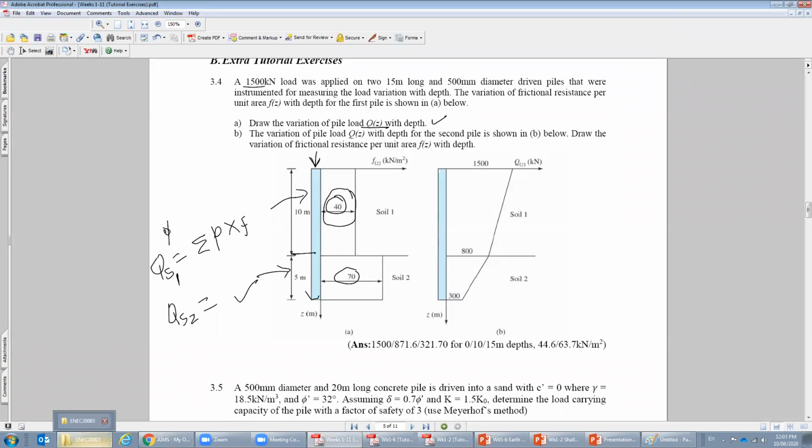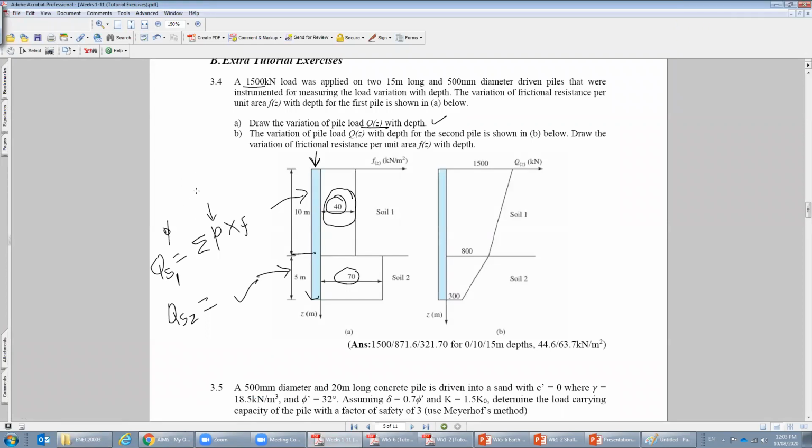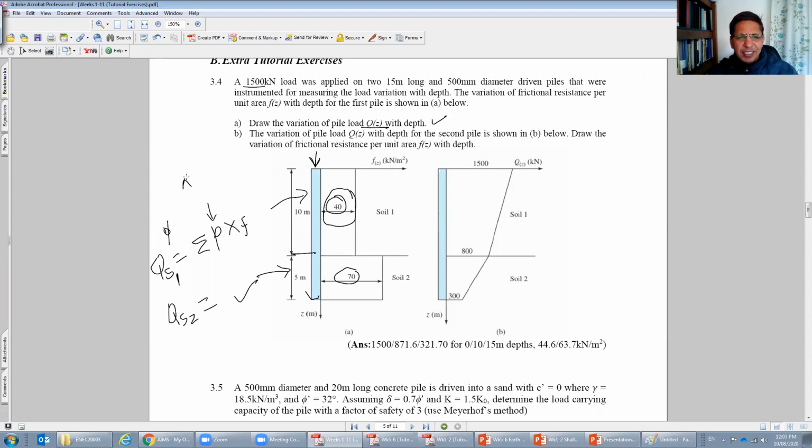During the calculation of QS, do we consider the length as well? Yeah, of course, length. Of course, perimeter comes, weighted perimeter comes with the length. This is perimeter, of course. Perimeter is where the friction is all about, right? Around, right? So that means what? I think pi, what is the circumference of this circular pile? Diameter, yeah? It's a circular pile, isn't it? So pi d is the around, and then multiply by length is the P. You see this one? So P.